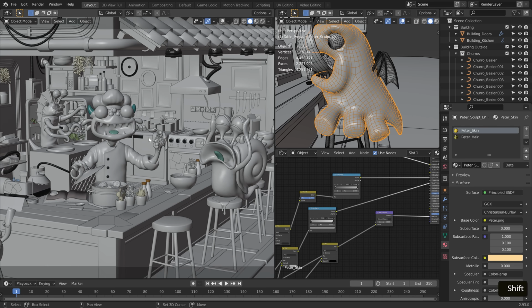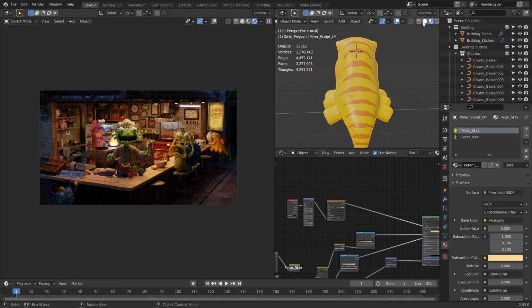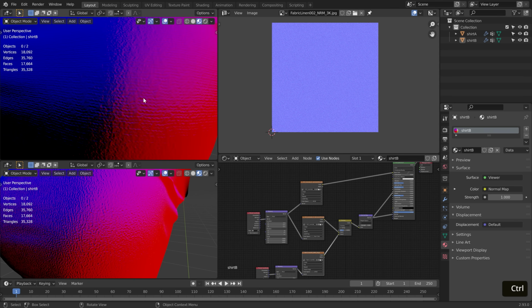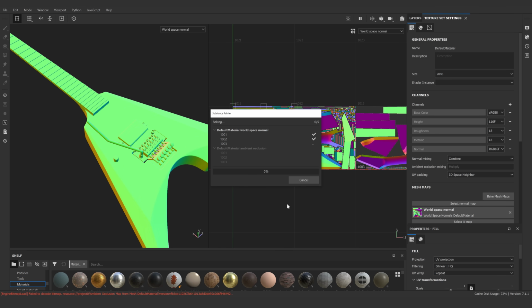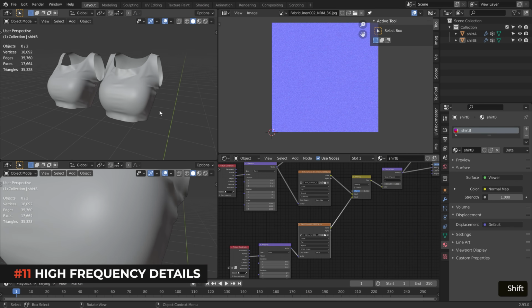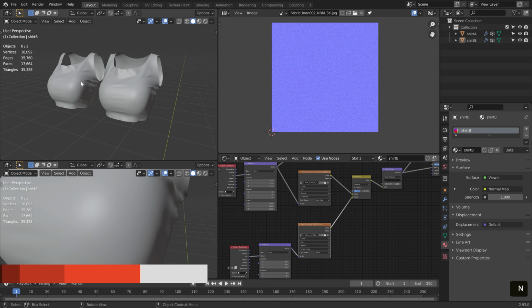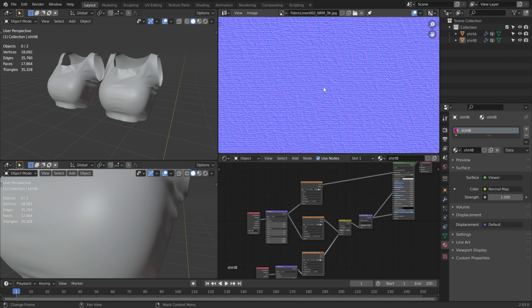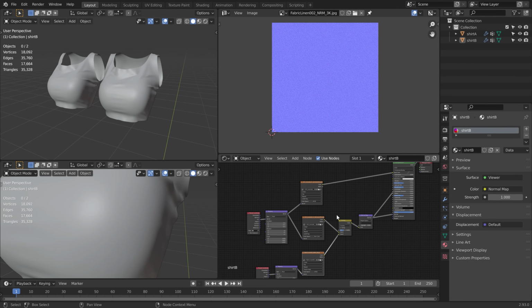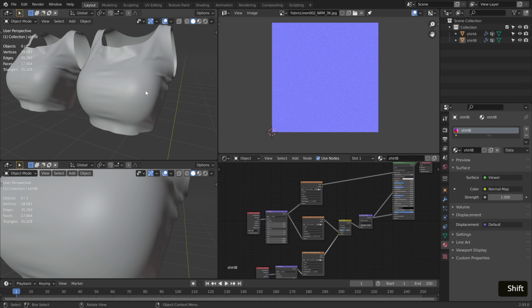Lastly, let's see some cases where you actually want to avoid using UDIMs as a solution. Otherwise, you could be wasting resources or reaching hardware limitations unnecessarily. The first case is tileable high-frequency details. Sometimes it is useful to split the type of detail you are using in your materials. If there is something that you just apply as a tile texture, it could be more efficient to add it on top in the shading network than have it baked in your UDIM sequence.